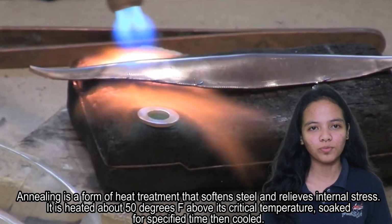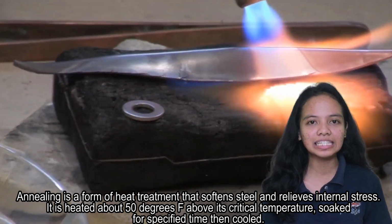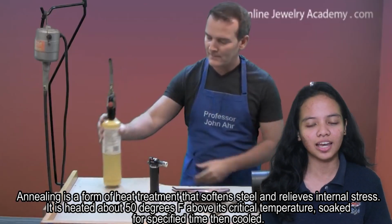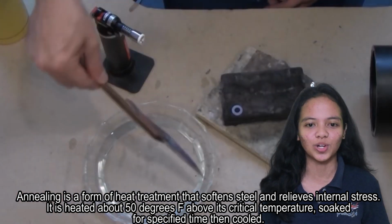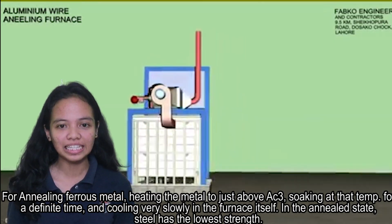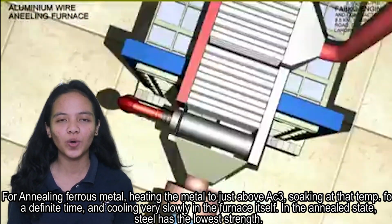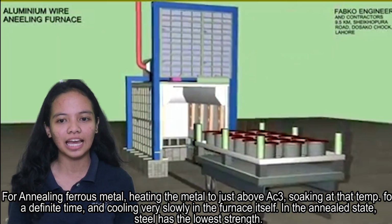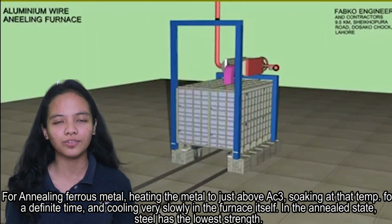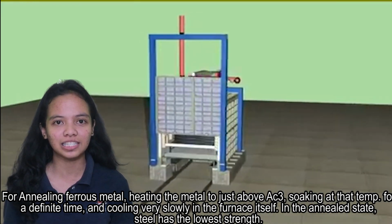heat readily. Annealing is a form of heat treatment that softens steels and relieves internal stress. It is heated about 50 degrees Fahrenheit above its critical temperature. Soak for a specified time, then cool. For annealing ferrous metal, heat the metal to just above AC3, soaking at that temperature for a definite time, and cooling very slowly in the furnace itself. In the annealed state, steel has the lowest strength.